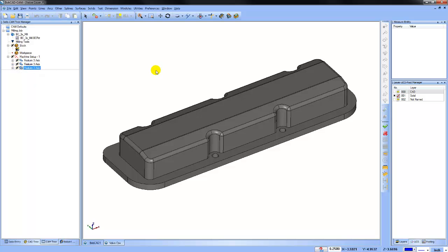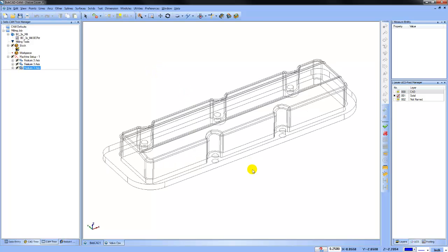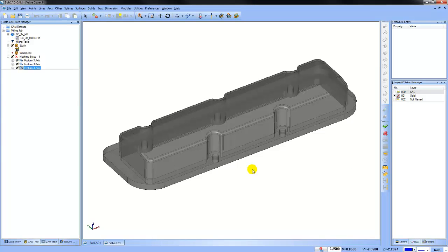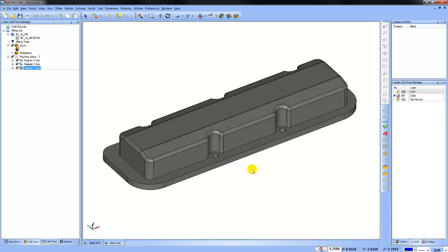Number 1, how do you toggle your shading on and off? So right now you have your surfaces and they're being rendered. If you hit S on your keyboard, you can toggle the shading. If you hit W, you can toggle the UV lines. If you hit T for transparent, you can toggle transparency, okay?